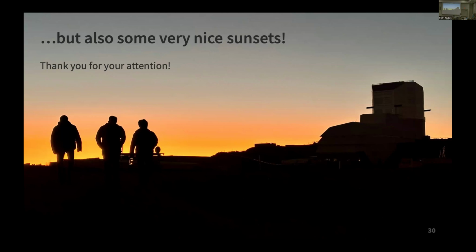Yeah, thank you. That's a great question. So we are moving it slow, and then we are going faster and faster and faster, and we are changing the movement of the telescope, and we are tracking the forces that the force actuators actually experience. So there are limits. After some forces, you cannot go faster, or you cannot go in that direction anymore, or you have to change the way you're moving the telescope. So it's pretty much following how the force balance system is actually responding to the movements that we are making.